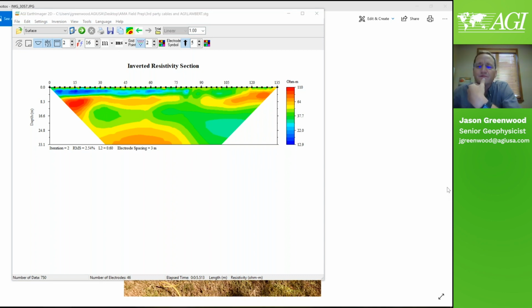Useful data, can you collect useful data beneath a plastic liner over filled cells? So plastic, of course, is an insulator. There's a leak detection method. There's an ASTM guideline where you place one of your transmitter electrodes outside the liner and one in a pond, and then you measure the potential across the pond, and any small pinhole leak in that plastic liner will show up as a voltage anomaly, and you can map that as a contour map. It's a very straightforward leak detection method that utilizes the insulation of the plastic.